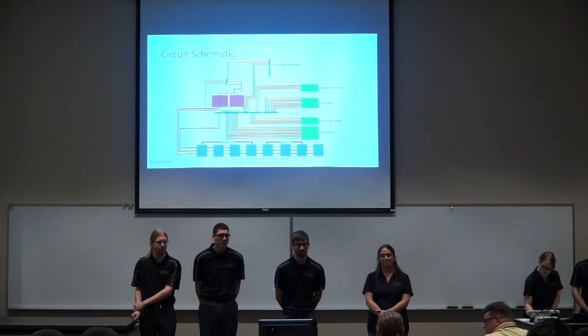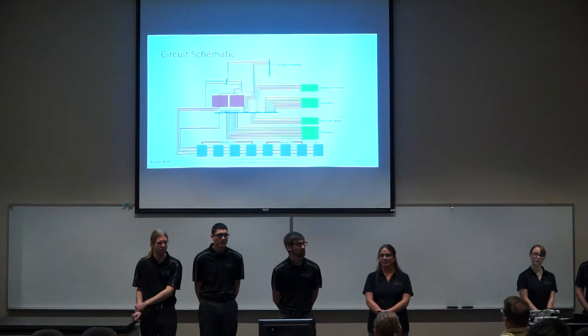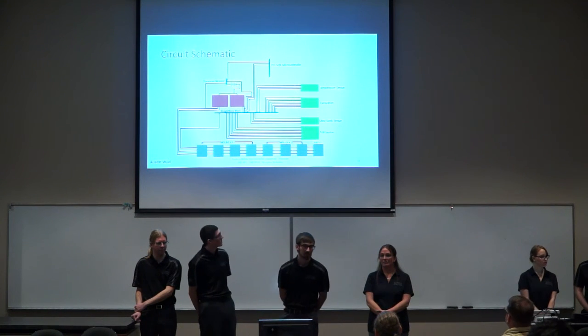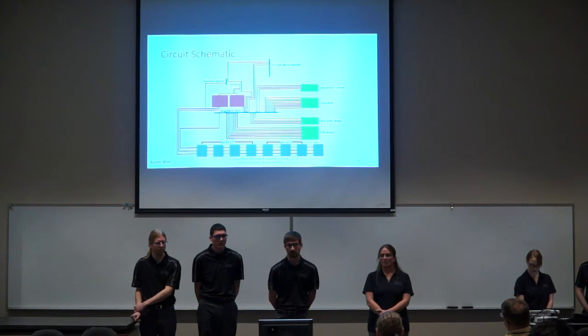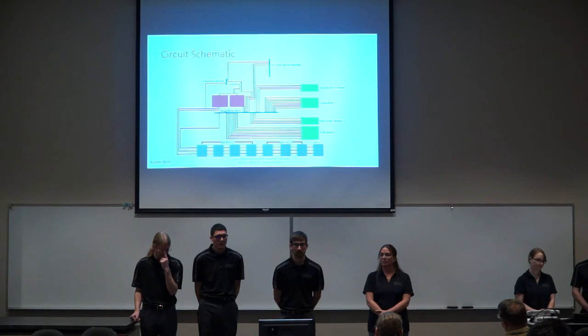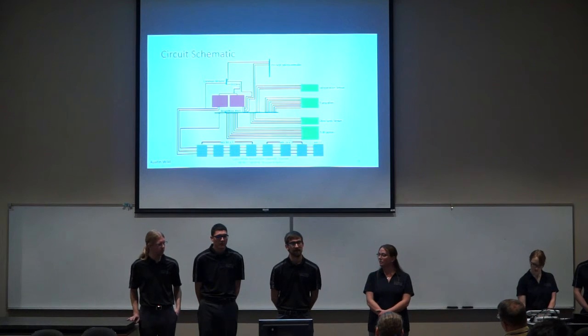So let's talk about significant additional information right now. Just one example here, the temperature sensor that you have on this block diagram. What are those three wires going to be? I don't think I understand your question. What are they connected to? What are they connected to at the BeagleBone Black bus? They'll be connected to, if I remember correctly, the 5-volt power pin, the ground, and then the analog to digital converter pin.